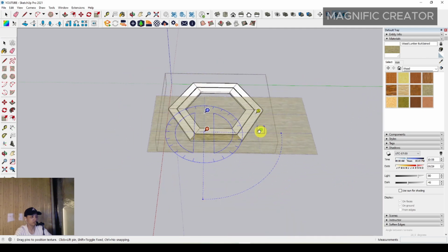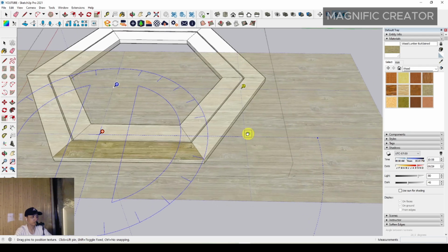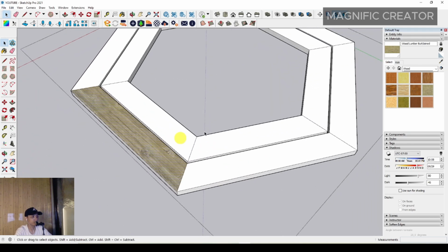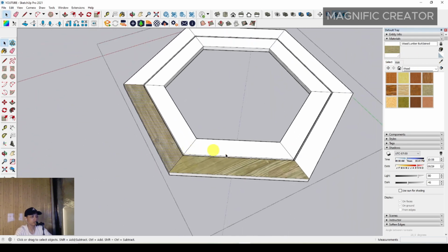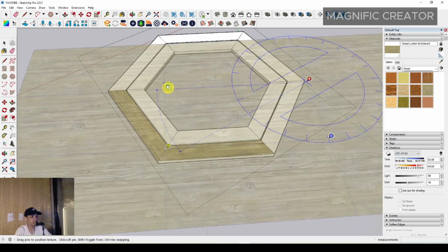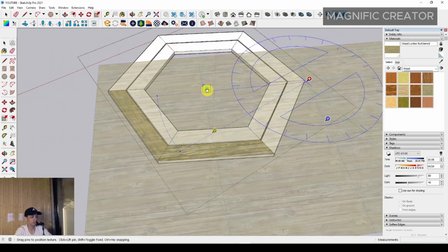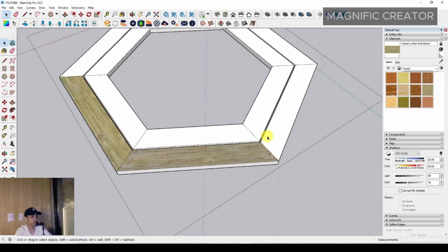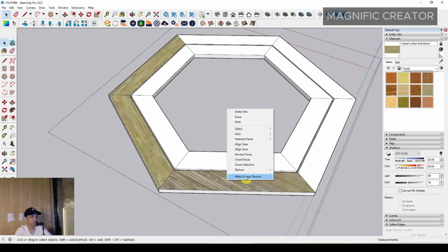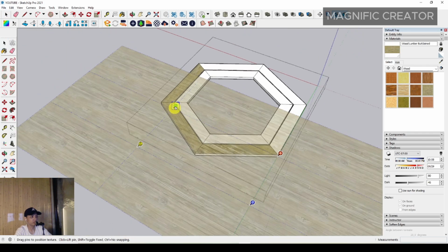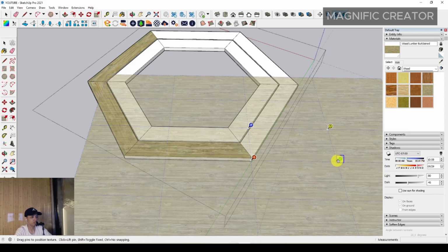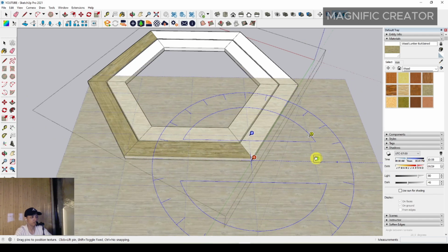Okay, and then we can adjust the scale of each material. Maybe we can adjust the scale, and then we can assign it again. We have to rotate the material one by one, so it will be a great result of material assignment. We assign again, right click, texture, position, and adjust the green option right here to make a better look of the surface of that bench.